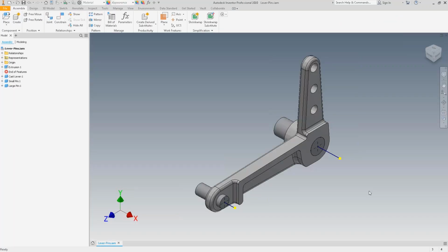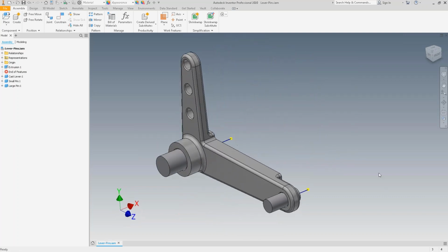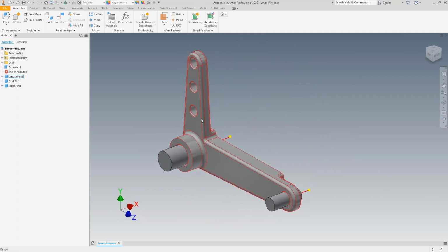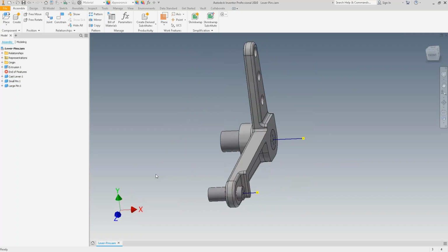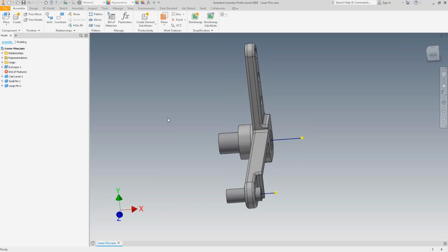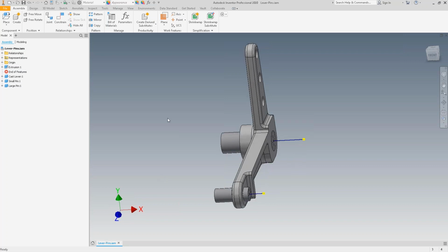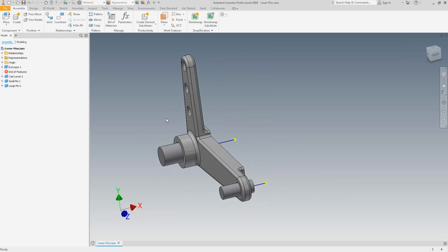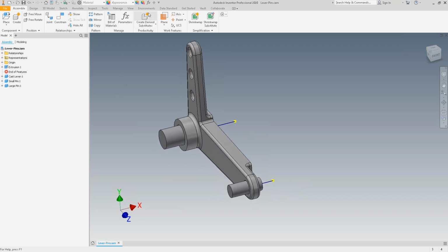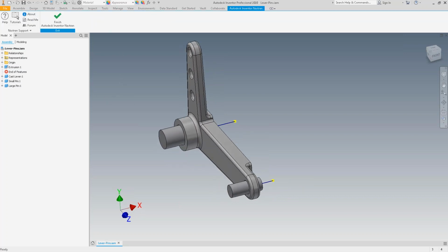Look at something similar, a little bit more on this particular type of mechanism. We still have the same cast lever, but now we've got the two pins in here that are going to be controlling it. In this particular example, we're only looking at half the model. So we could actually set up some symmetry in here, run the analysis on half of the design, and save some time. If it's a symmetrical design and symmetrical loading conditions, then of course the stresses are going to be symmetrical as well. So when I come into Nastran for this one, same thing still applies.